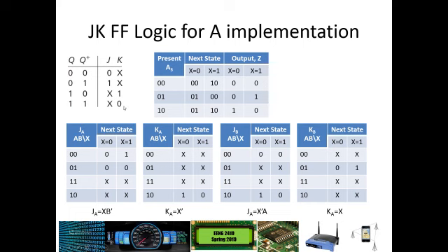And so down here, what we're going to do is derive the logic for JA and KA and JB and KB. What you'll also notice is we are not using 1, 1 as a state representation. So across all 4 of these Karnaugh maps, the 1, 1 row is filled in with don't cares, because that is not a possible state. We can never get to that state, so we don't care what the next state representation would be for a state that we can never possibly reach.